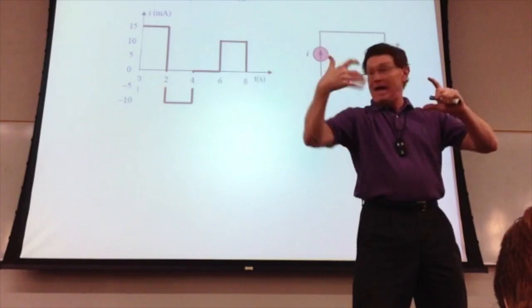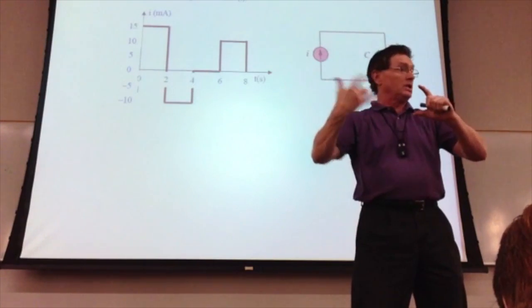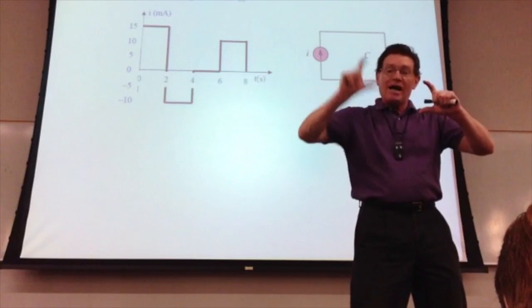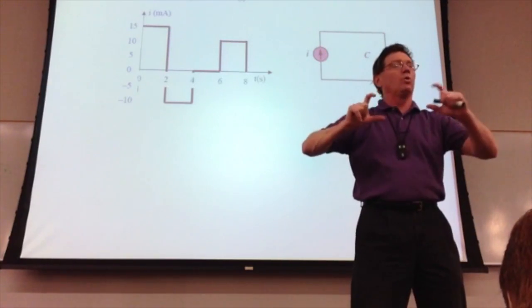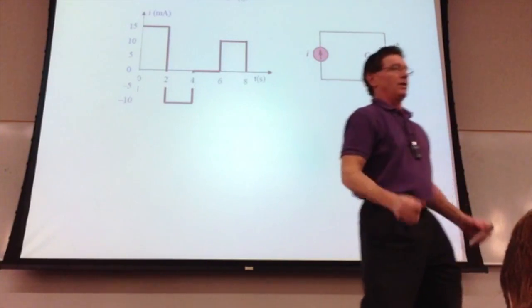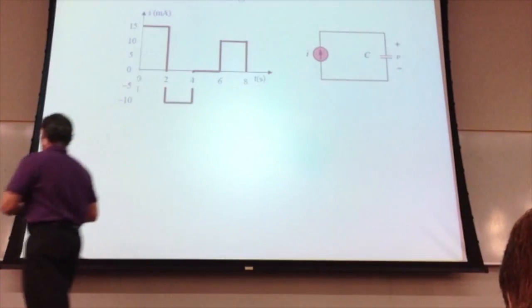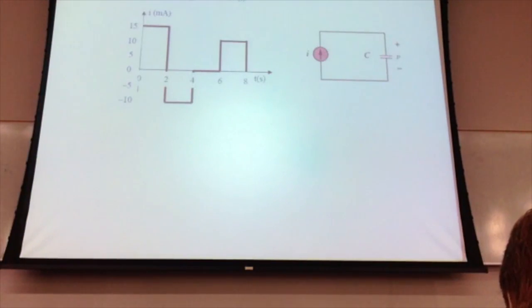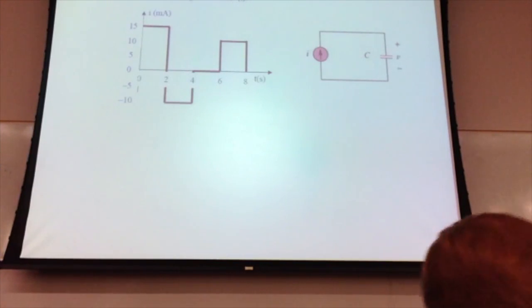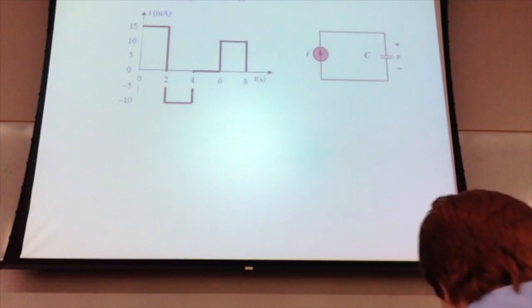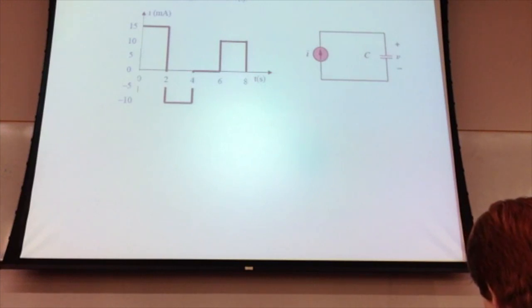The magnetic field, it's an amazing thing. It's one of these things in nature. If I have a time-varying magnetic field near a coil of wire, it puts a current into that wire. So if I have a DC current here, I have a constant magnetic field here, will I get a current in the second coil? This is a constant magnetic field, not a time-varying one. What will happen? I won't get any current on this side.